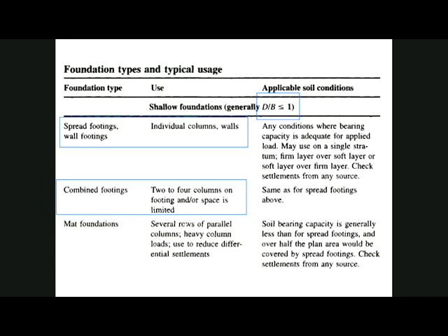We usually consider spread footings for soils which have a high bearing capacity, since our goal, aside from reducing the settlement, is to make sure that the soil will not fail once we apply a certain load.